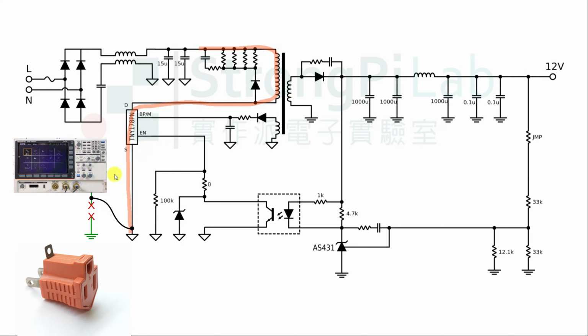People may say, how about removing the ground prong of the plug, to prevent the circuit from blowing out? It will be much easier. Oh, no way. It is solely for this particular case that we cut the scope's ground. In the case of measuring the PSTN phone line, the scope has to be grounded. You can check the phone line topic at the upper right corner. We have to use different settings for different situations.